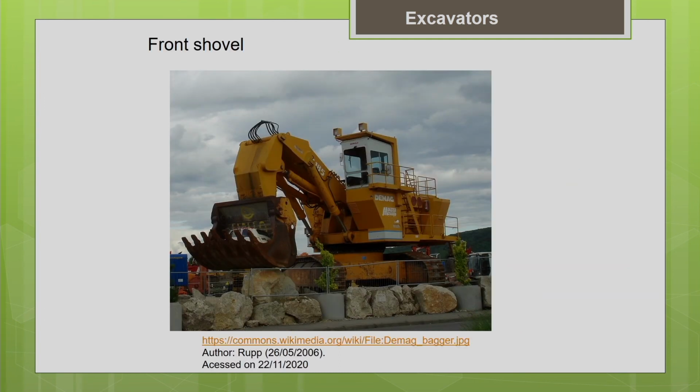So, let us first discuss the front shovel. This picture shows you a front shovel of very huge capacity. Basically, these shovels are fixed position excavating machines. That means they are not designed for much mobility. From the loading to the dumping position, it is not designed to move. It will just swing its boom from loading to dumping position. That is why we call them fixed position excavating machines.